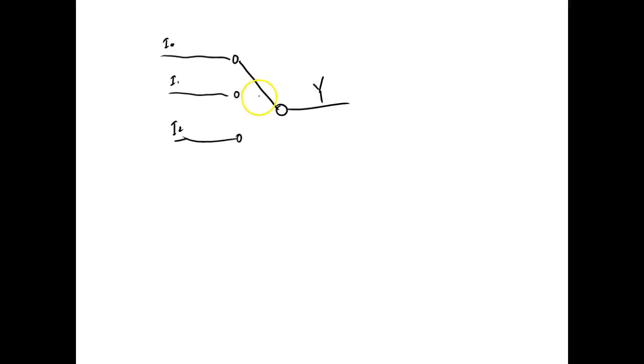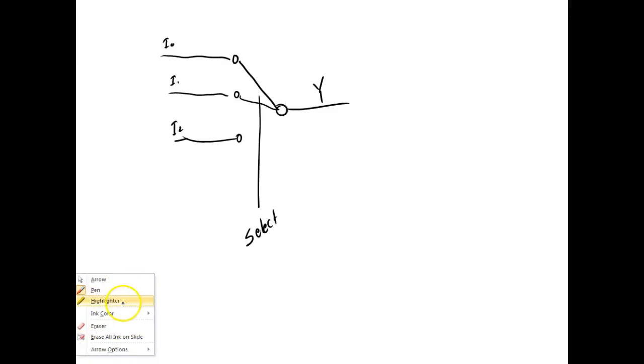But what I'm doing is changing the position of the switch with my select inputs. So right now, if I've got it in this position, what comes through? Well, input 0 would come through to the Y output. If I switch it down here, input 0 is not going to come through anymore because I've selected what input? I've selected input 1. Understand that? So we're electronically switching those switches with those select inputs, S0, S1, and S2.